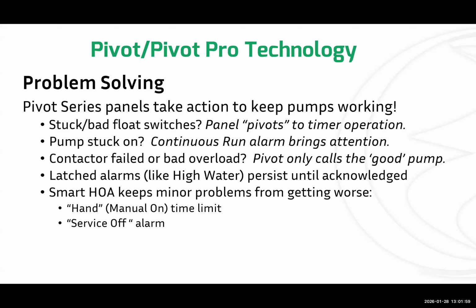So I mentioned that we want to prioritize running the pumps. We want to make sure that we keep those pumps working even when bad things happen. And so again, if you have floats that get stuck or otherwise go bad, that panel will pivot to a timer operation from just relying solely on the floats. If a pump gets stuck in the on position, or if a float gets stuck up and doesn't drop out, and so it just wants to continue to run, it'll tell you, hey, this system is running longer than it should.